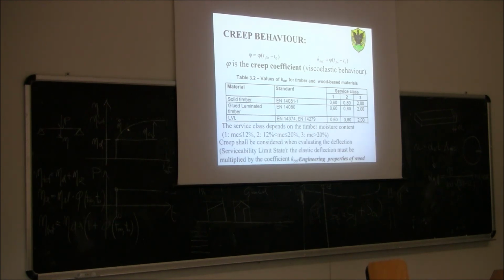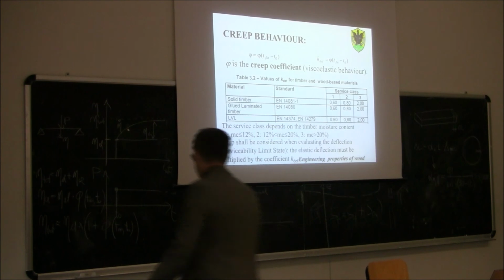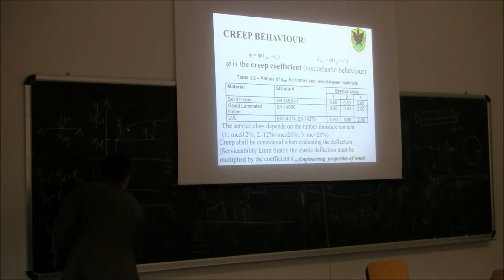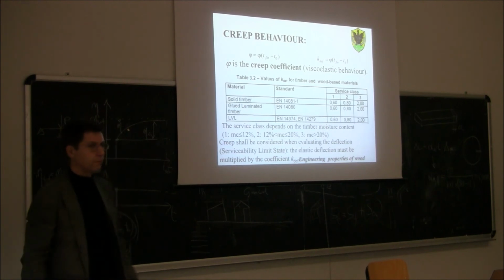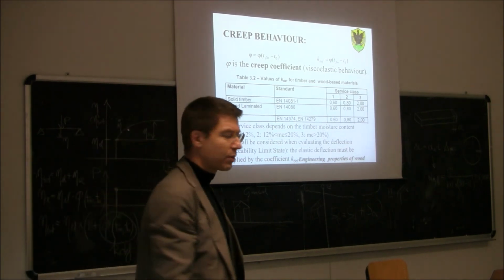Of course, creep shall be considered when evaluating the deflection, for the serviceability check. The elastic deflection must be multiplied by the coefficient kdef. As we said before, elastic deflection times kdef will give you the creep, plus the elastic deflection will give you the total. For timber, we will use the same formula except that we will replace φ with kdef. Otherwise the formula is the same.